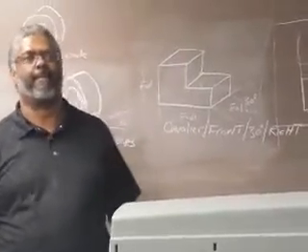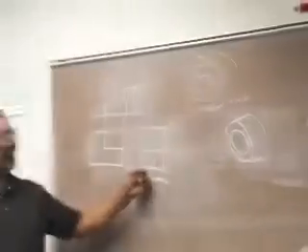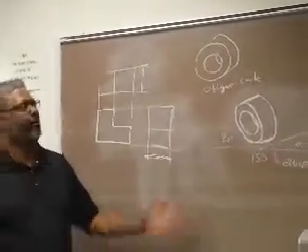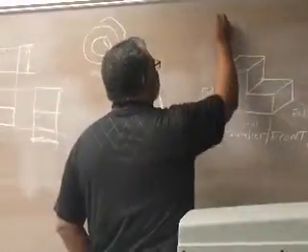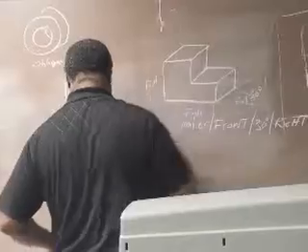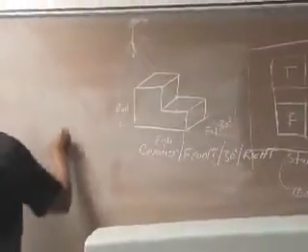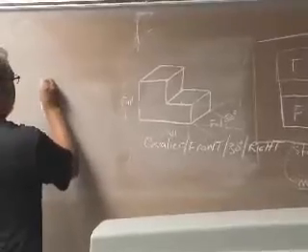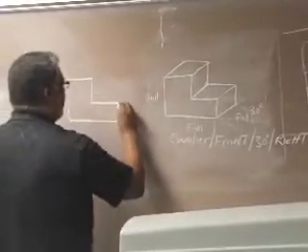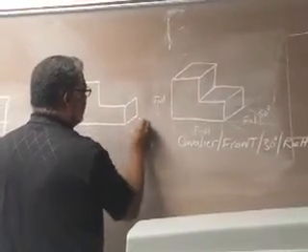When we draw a cabinet, do you just take half a measure? Right, you're doing half the depth. Whatever the depth measurement is, you're halving it. So if I were to do this as a cavalier, everything's the same except we're going back half this distance.